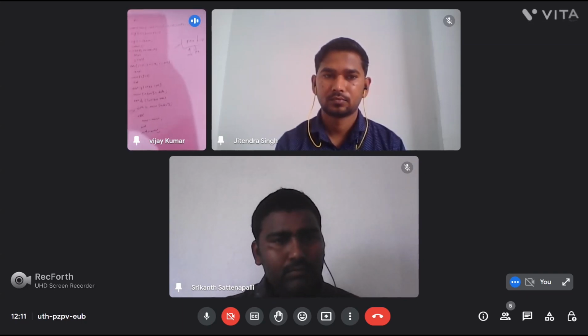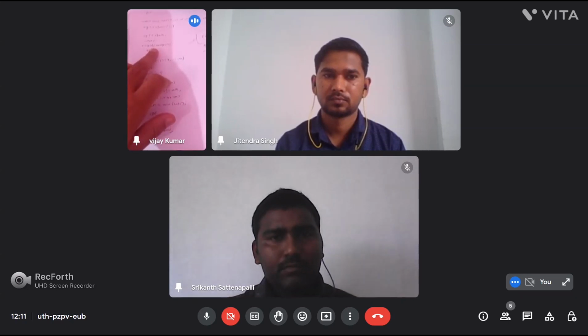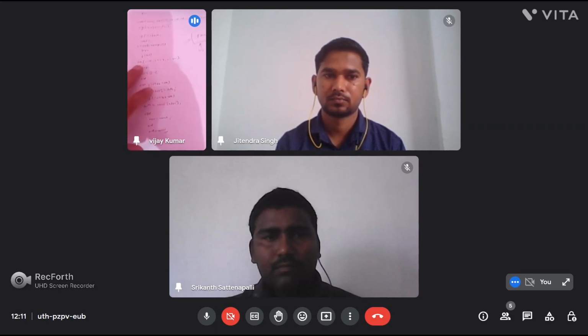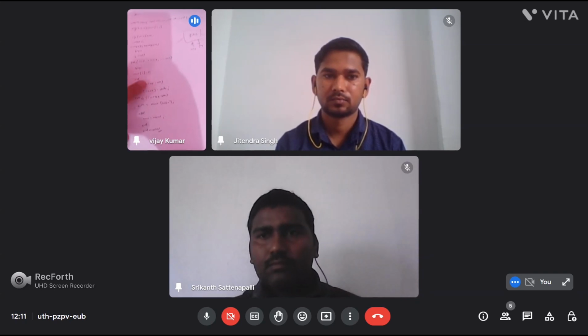Yes, sir, I have done the code. I have taken 4 memory locations, and each memory location can store 16 bits of data. At the positive edge of the clock, I started the program. If reset is high, then all memory locations should be 0. Otherwise, I take an else if.